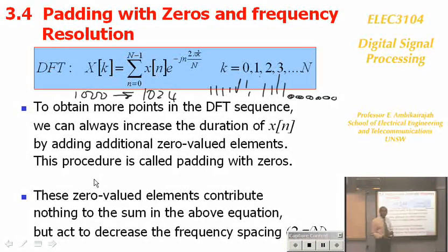By adding zeros, you are not changing the amplitude of the waveform. If you think about it carefully, no, you're not. That's called padding with zeros. By adding zeros, you are making the number of samples 1024. That allows you to apply the fast Fourier transform. And not only that, look here. These samples are that, and by adding extra zeros, you're not going to change the summation. So you're not affecting the summation.